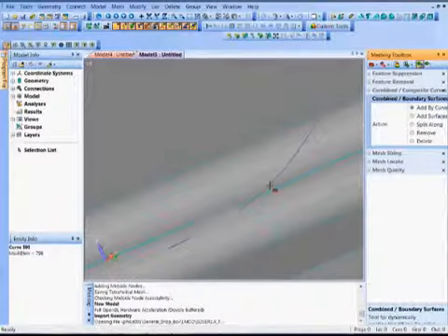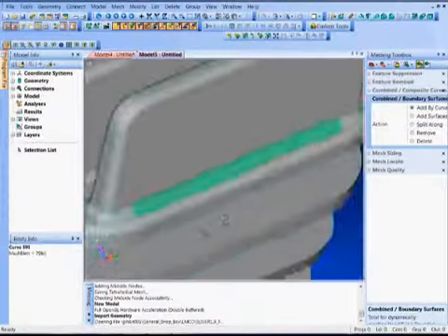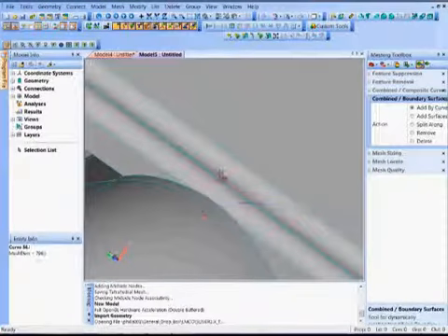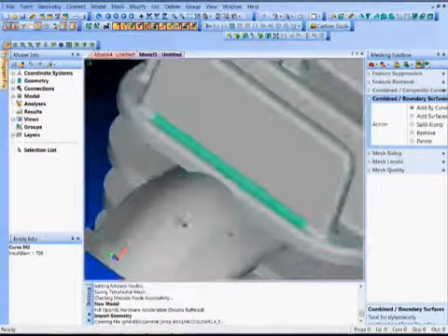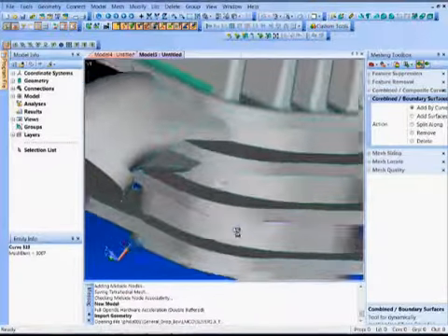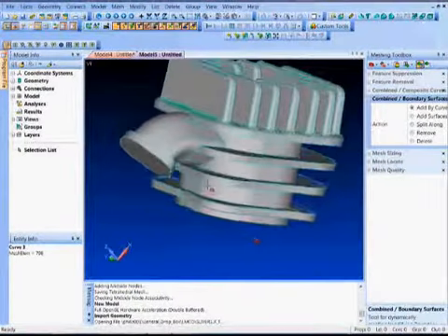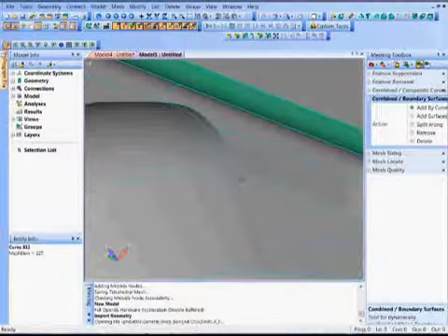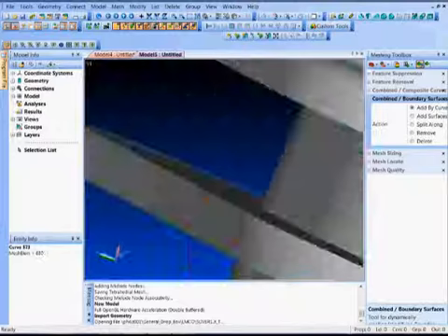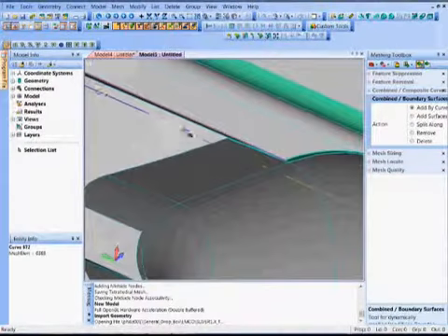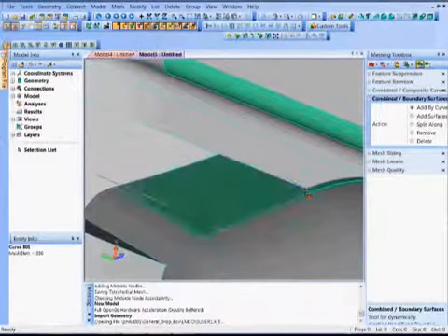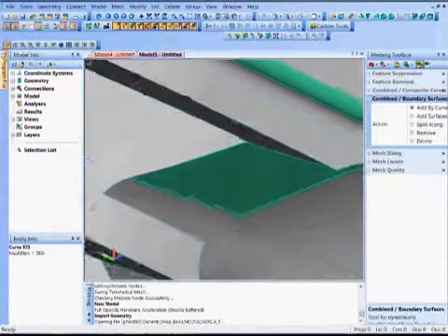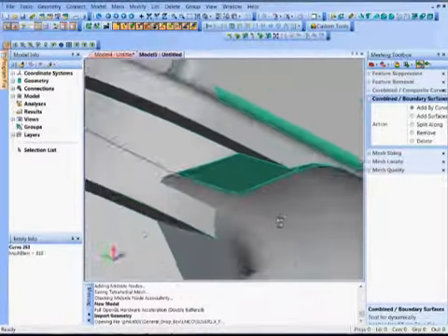We just pick a curve, and FEMAP actually just connects the 2 surfaces together. So we do the same thing there. Same end effect as what we did before. Do the same thing over there. And now we basically just combine those 2 surfaces. And then we also want to do the same thing with that little undercut in this edge here. So we'll basically just pick it, and that combines all that into one surface. And we can even run that right over here to the other side. And now that's all treated as one surface, kind of pulling that little ledge off.